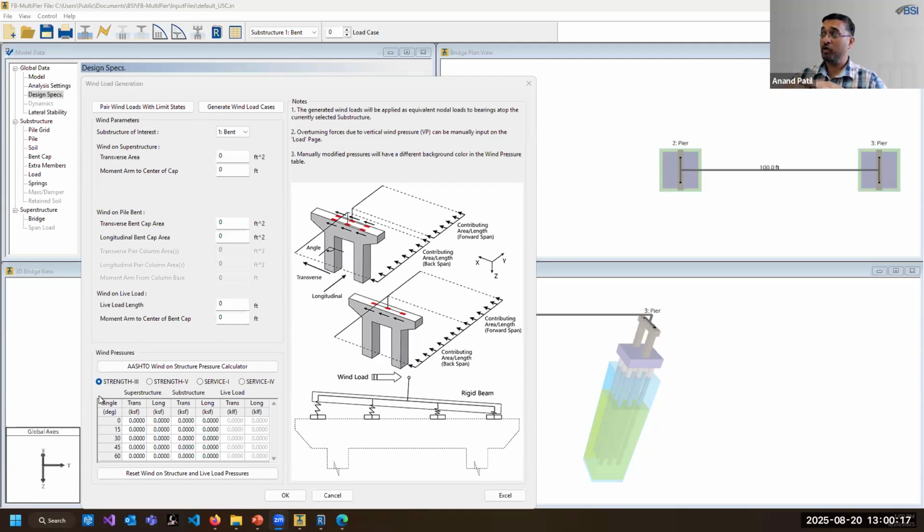For the pier cap, which is a shell element, unfortunately we don't have an inbuilt way of getting that thermal deformation in. But that would be a nice add-on. If you guys are using that, I think I have another question that somebody asked about the same thing.